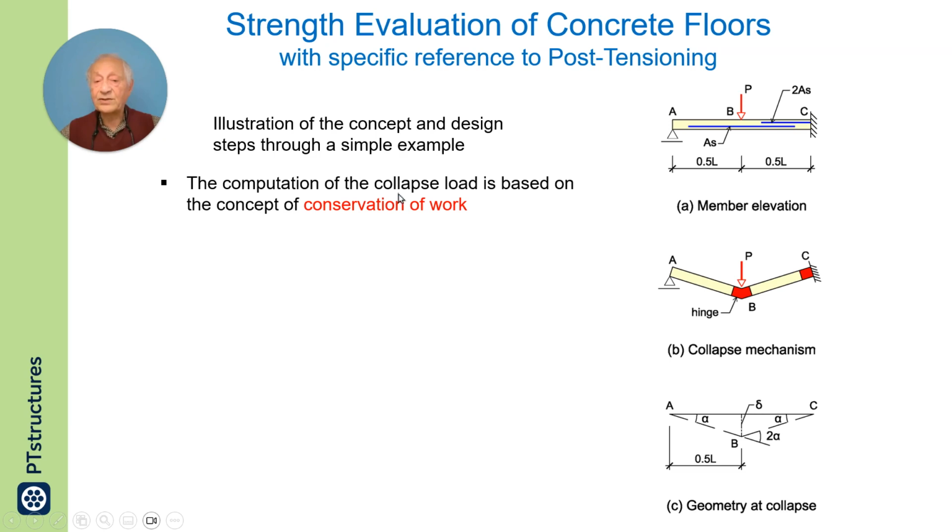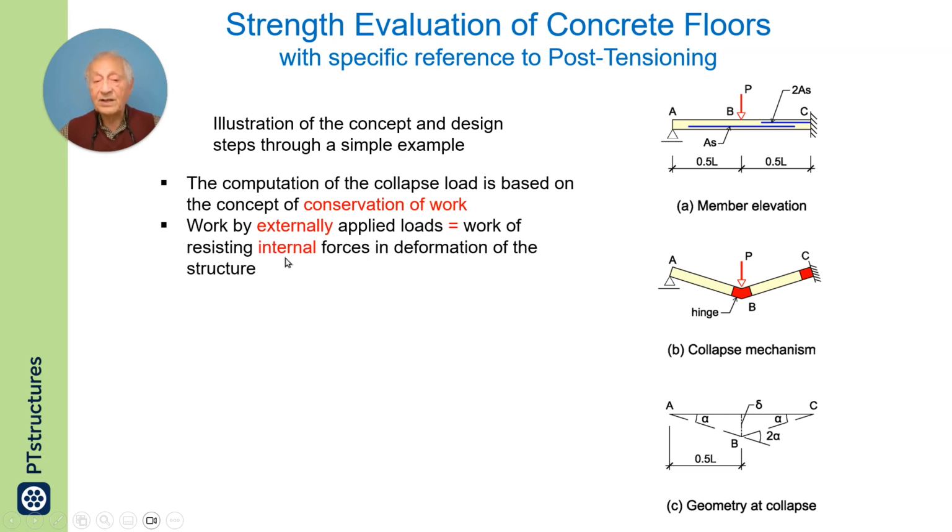The computation of the collapse load is based on the concept of conservation of energy. What does it mean? It means the work done by externally applied load in its displacement, which obviously is force times displacement, must be equal to the work of resisting internal forces in deformation of the structure.